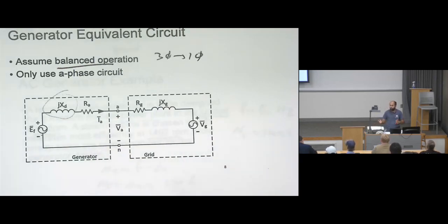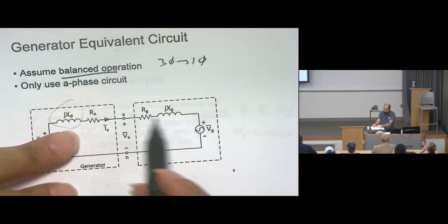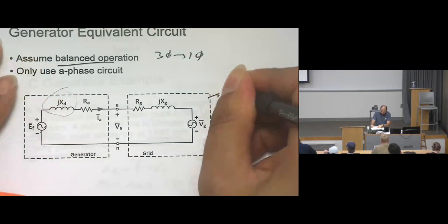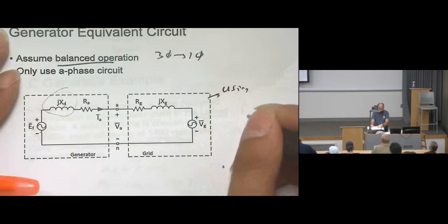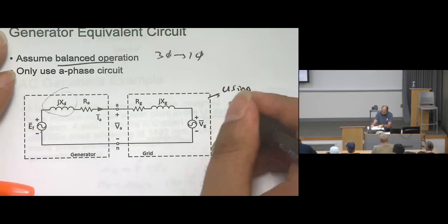As a shortcut, we reduce everything to a voltage source and impedance. This is how we make a shortcut using R Thevenin and V Thevenin. Do you remember this? All of the utility grid can be converted to R Thevenin and V Thevenin. So we will have RG, VG, XG, using Thevenin. The derivation you are not required to do, but just for your information.